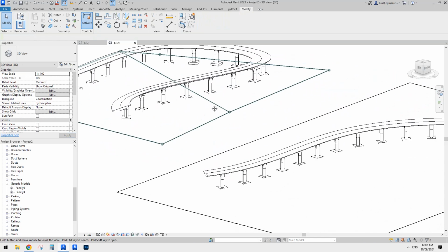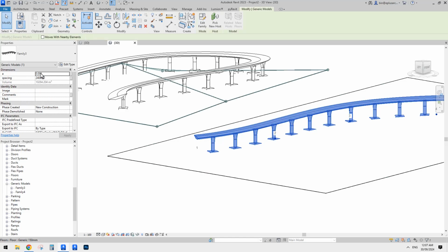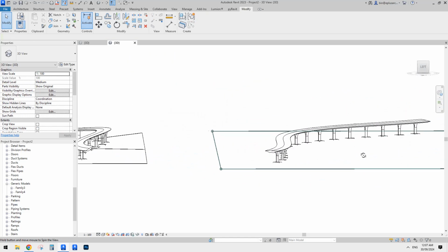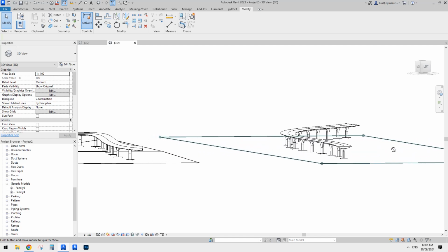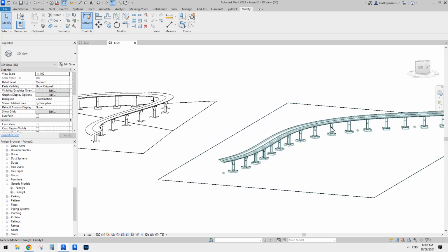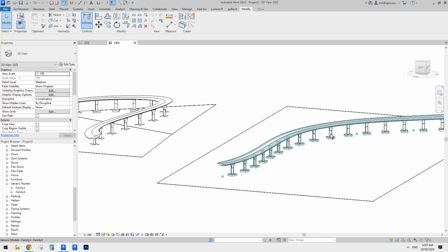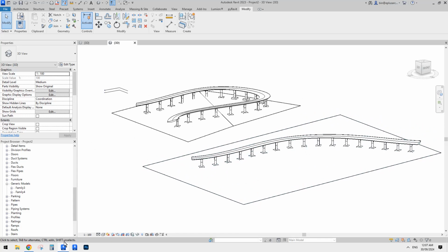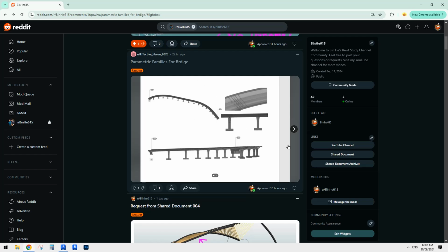Yeah, great. So now this one is currently 0, which is correct. Yep. So we don't need to have different families. We can just create an instance parameter for the nested adaptive family. So I think this is it, and then the rest is quite straightforward.